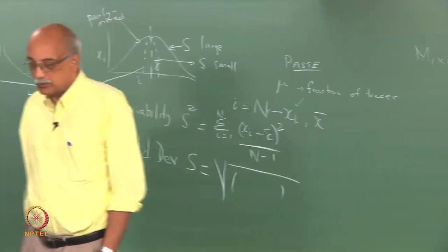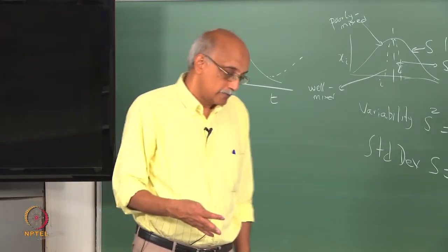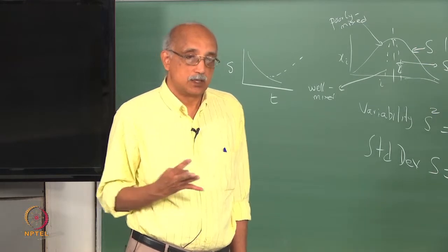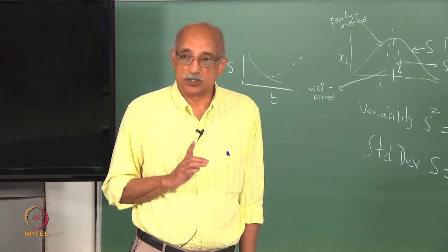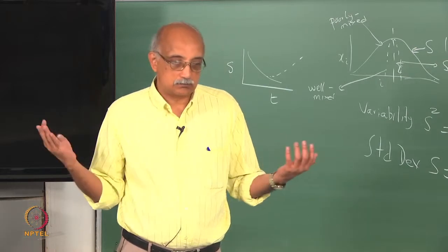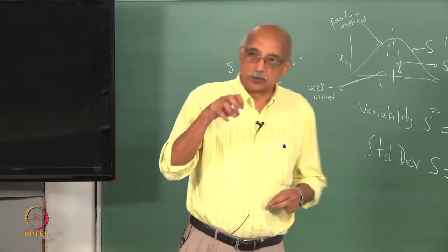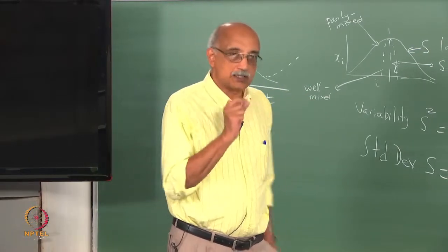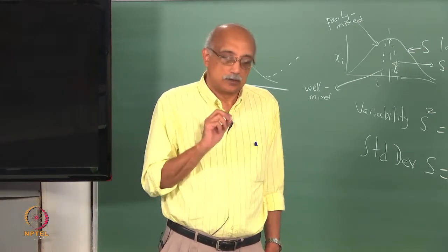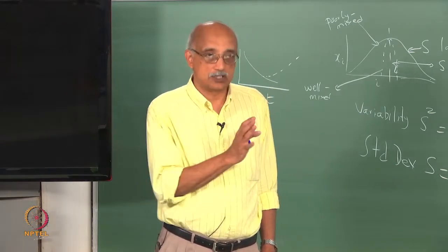In the case of a mixture of two solid materials, the reference value is what is known as the equilibrium or fully mixed standard deviation, which is not equal to 0, because the difference is that when you are mixing, say, sand and salt, again when you take a sample from this, depending on the size of the sample, each sample that you take may have a different ratio of sand to salt even in a well mixed powder.